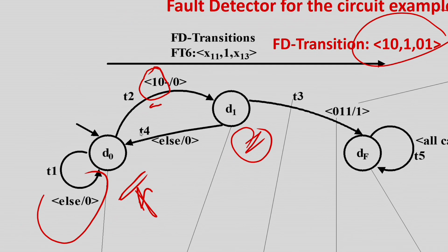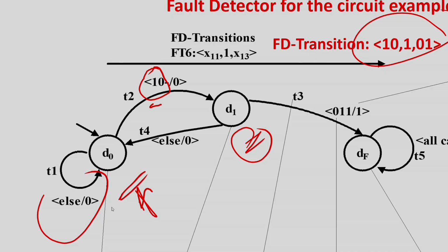So what I am doing is, initially it is probing all the 3 lines, V1, V2 and V3. So V1, V2 is 1 0, that means the circuit is next going to be in the state called error detecting state, that is 1 0. So in this case you will go to an intermediate state of module 2, that is the tester. It is very happy that the fault can be detected from this next state, otherwise it cannot do anything, it will keep looping.